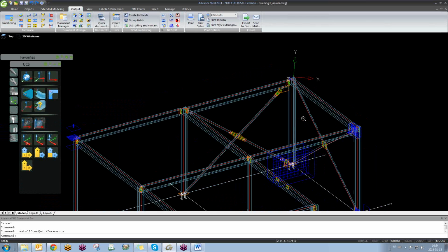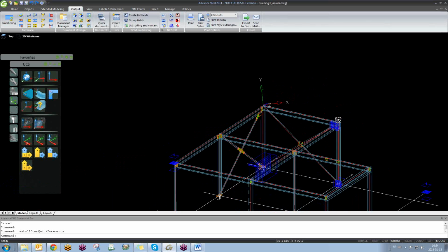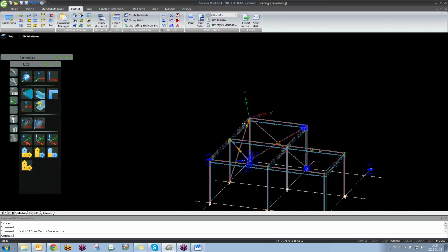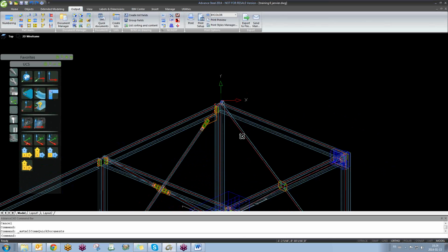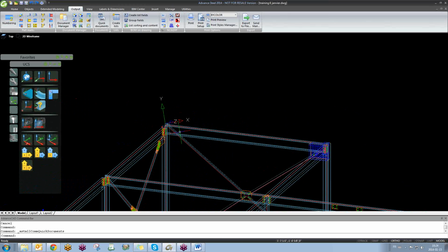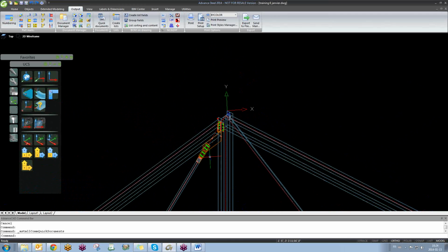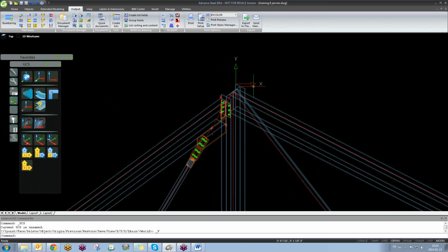You can absolutely create a camera within this UCS. That's the best part. For example, if you want to just have this part here without deleting the stairs, as you were saying, you can just put the UCS right where it is, or put it to view again just to see it this way.